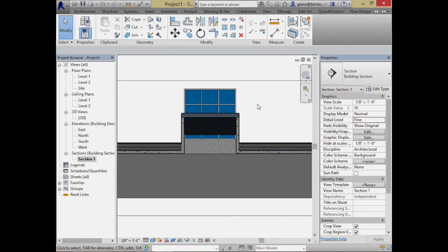It's just going to hit the center, kind of what directly can be hit with the rays. Okay. What happens with these little surfaces, though, is they give you a little reflection surface. So the interesting thing then is, as the sunlight comes in, it not only radiates down, all the sun that would just sort of hit the roof actually hits the little white sidewall and bounces back. So it's weird, you actually capture more sun by putting a wall that's a reflecting surface in than just having it be all by itself.